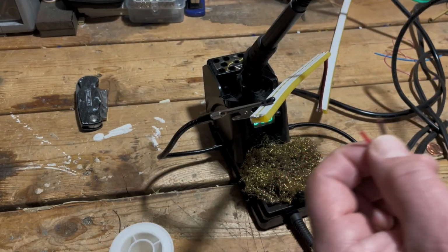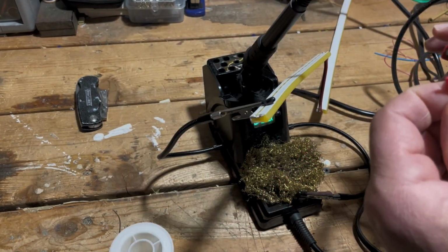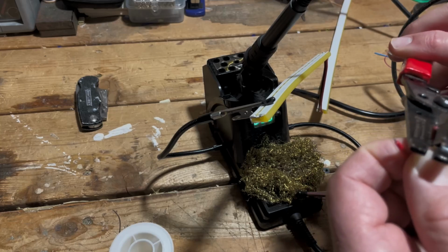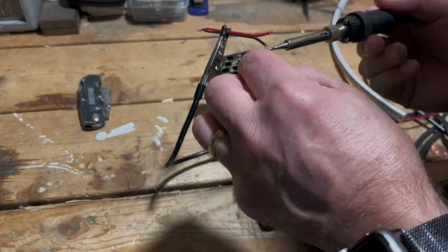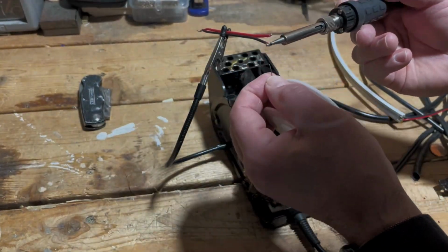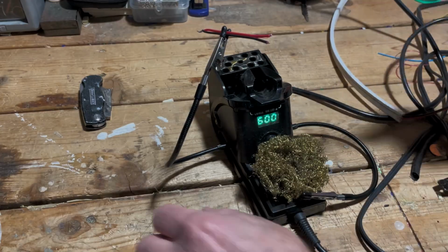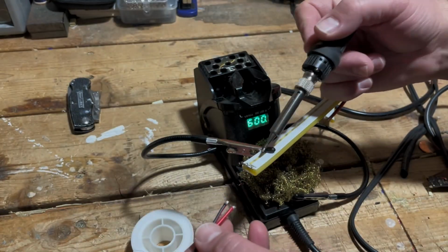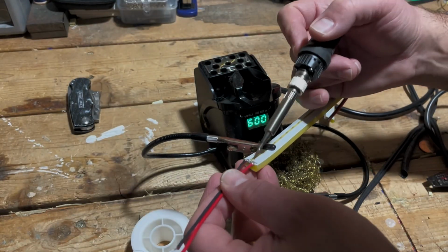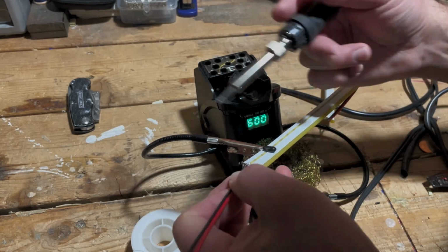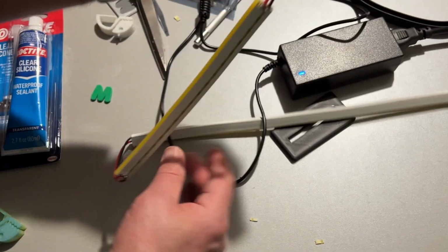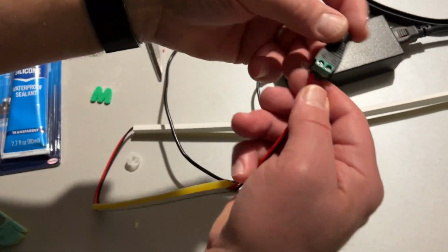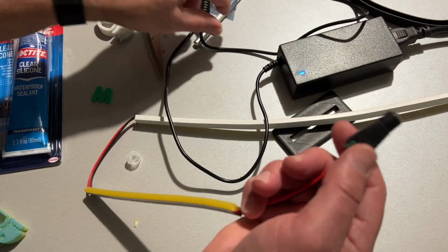Grab another of these wires, and we need to extend the ends because we're going to use this to connect to the power source. Of course, let's tin the ends of that to make the process easier as well. Once again, we're going to connect the red to the LED side and make sure the connection is secure, and you're done. And friends, there they are with those wires tightened in.